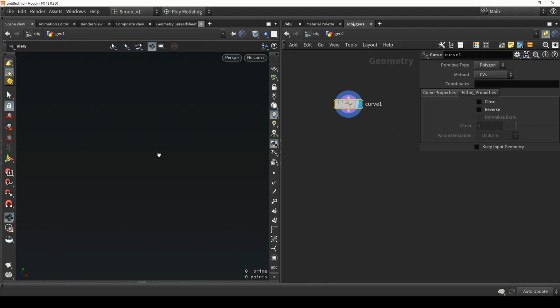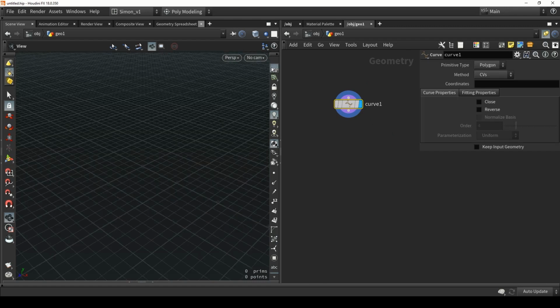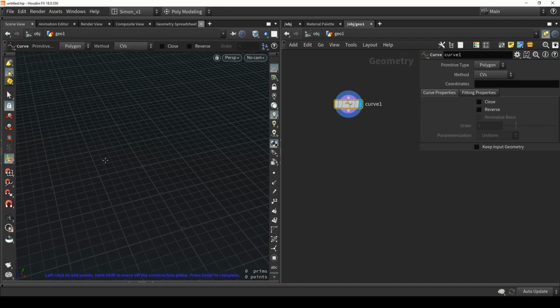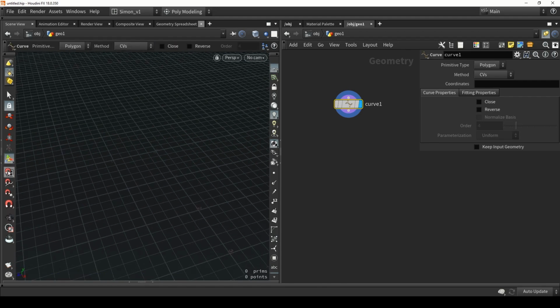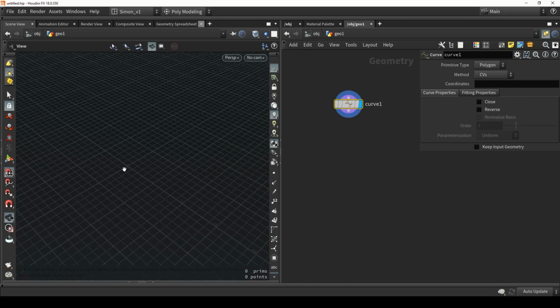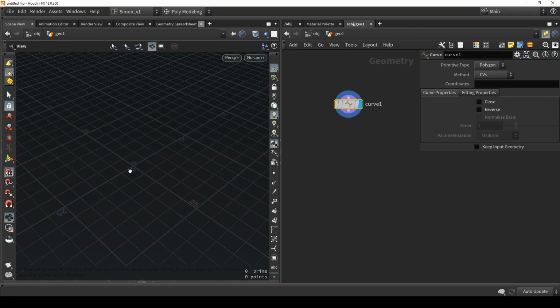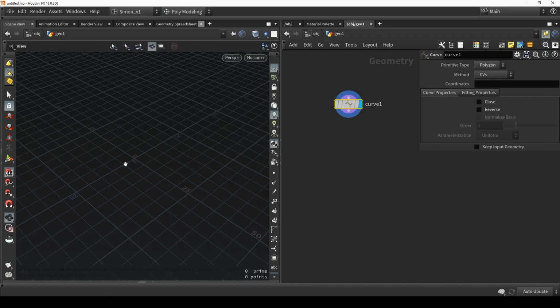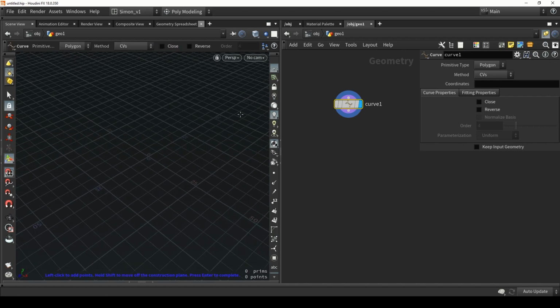For the moment, I want my curve to be nicely on the grid, so I'm going to enable my grid over here, and I'm going to also click this handle to then actually create the curve. And one more thing is the snapping, so the first snapper over here is grid snapping. One important thing is that we zoom out until we have a decent range, and now we can draw our curve. If you stayed in a very small range and loaded the tool in Unity, you would have a very small level builder tool. So we're going to zoom out maybe like 50-50, so it's enough space, and let's just draw a random line like this, for example.